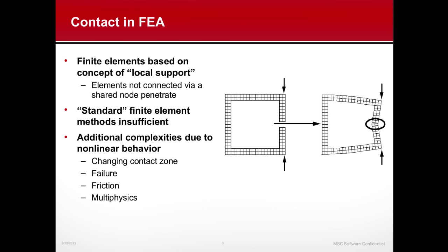And with the nonlinear deformations, engineers also need to be concerned about the changing contact zone and pressure because as it changes, the deformation and the loads change. And also even the failure of the material. For example, if you have a crack propagating, your contact zone has changed at that point, and there are some new elements, new nodes that get created, which also may need to be checked for contact.